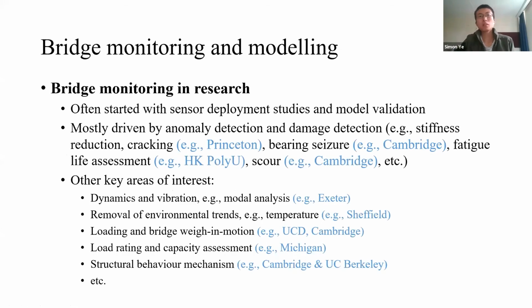So let's first look at research. Bridge monitoring in research often started with sensor deployment studies and model validation. By sensor deployment studies, I mean validating the measurement technologies we developed or we have. For example, to what degree of accuracy and precision can we measure various types of bridge response. And then we go to model validation, where we compare our measurement with model predictions to see how accurate our model is in predicting the performance. But these two alone are not structural health monitoring.